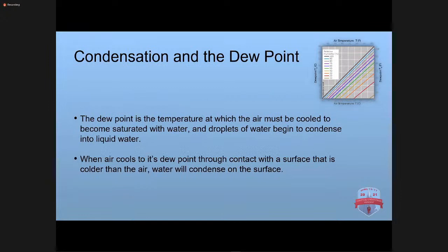And condensation. This is something that a lot of people take for granted, particularly if you're operating where it's much cooler outside. Say, for example, during the Christmas holiday, if you're in a latitude where it does snow, you need to worry about introducing hot, moist air in contact with things that are cooler, basically below where the dew point is.